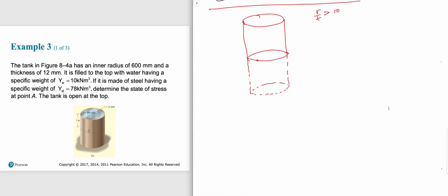So whenever we make a cut, that means whenever we take only the part till A, because we have to make a cut to see what is happening at A. So when we make a cut, we have to write normal, we have to write shear, we have to write moment, right? Always you have to do three things, isn't it? Normal, shear, moment.